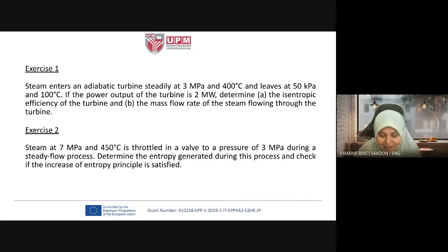Okay, adiabatic. Actually, sometimes if it's not an adiabatic turbine, there is some heat exchange, Q, within the turbine, but usually it is smaller than other components, work or enthalpy, so sometimes we neglect it. But here it's clearly stated that the turbine is adiabatic. So we can assume no heat exchange, no Q, the Q is negligible.